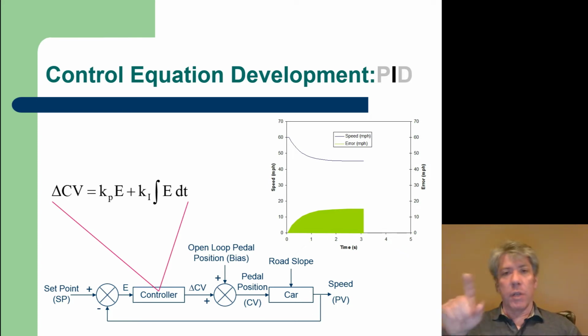And when we come back through the loop, and we calculate again, how much error is that? Multiply by the amount of time since the last time we checked, add that to the pile. That's all we're really doing. And so if you look at the graph here, what you'll notice is that the integral term is represented by the shaded green area under the error curve. All that the integral term does is add up area underneath the error term, or under the error curve. And notice that that area gets bigger and bigger as long as error hangs around at a non-zero amount.